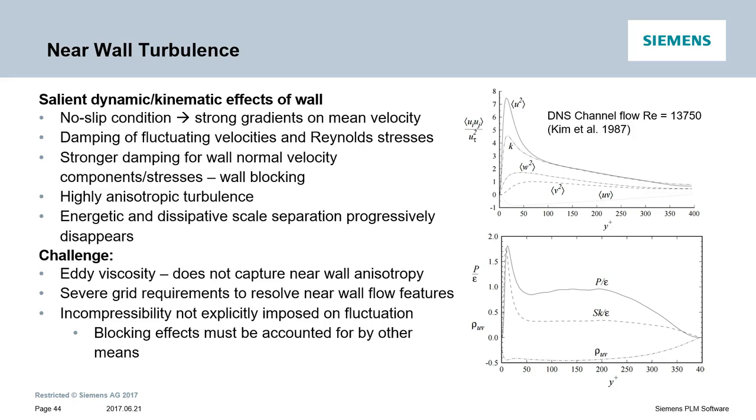Now you may ask why we worry so much about the turbulence near the wall. What about the mean flow? How does it naturally behave near the wall? The answer is, after using Reynolds decomposition, this effect is inherited by both mean velocity and fluctuations.